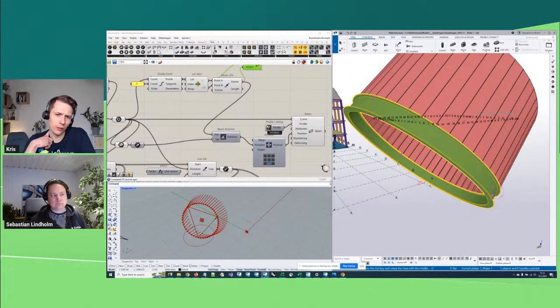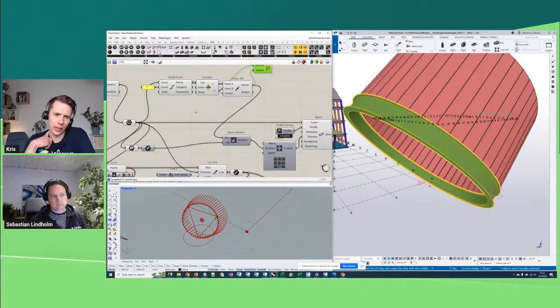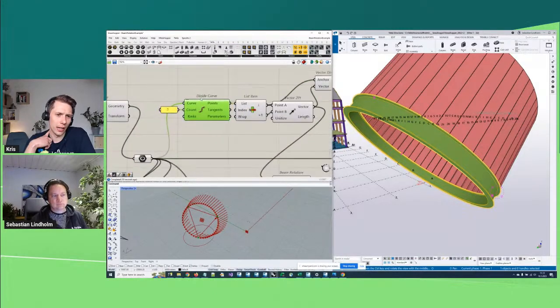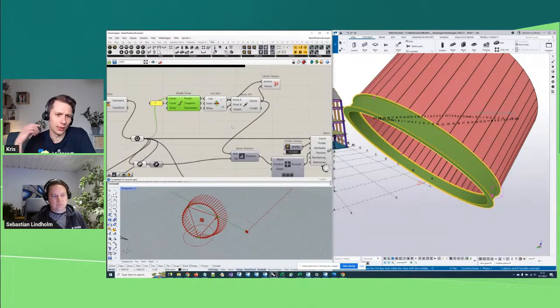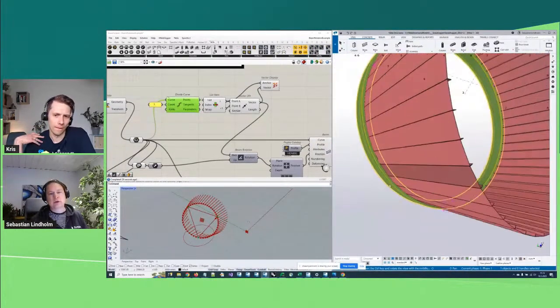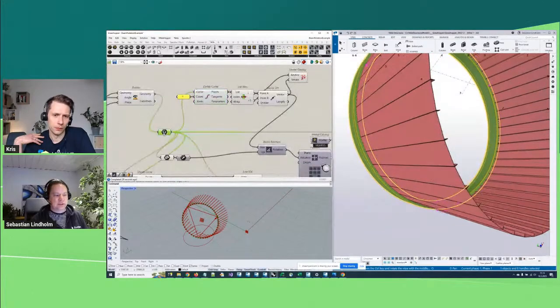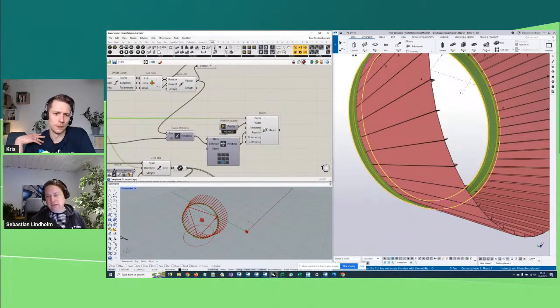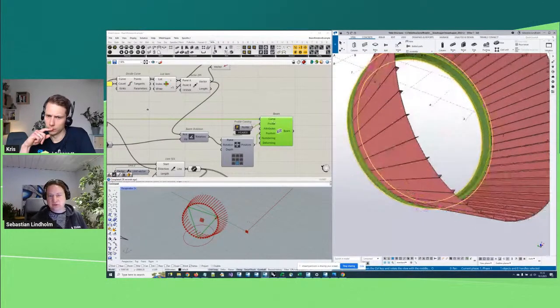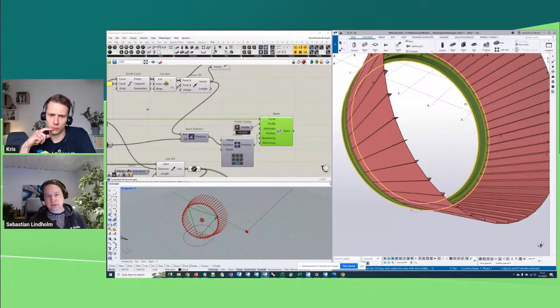So when you are going to divide this curve by 3, to the 3 elements, actually Tekla is defining these 3 elements as well. So it's always taking equal segments, right? Yeah, it's pretty much the same algorithm, because here it's still a mathematical circle, but in Tekla everything needs to become segmented. So internally, what the beam component does is it recognizes that it's a circle as an input, and it creates these 3 points equally spaced and puts the arc chamfer type on them, and then you get this representation in Tekla.